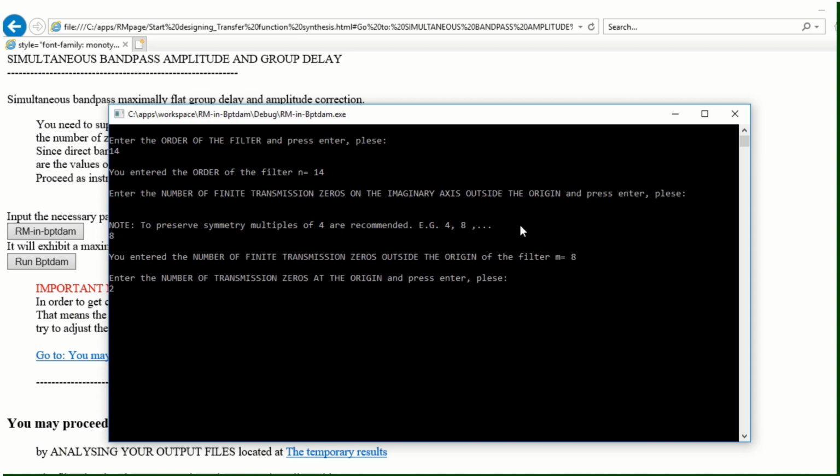One should have in mind that the negative image of the amplitude characteristics is more influencing the lower part of the positive frequency response, so that by putting 2 zeros in the origin and leaving 4 zeros at infinity, we are trying to make some balance to reach symmetry.